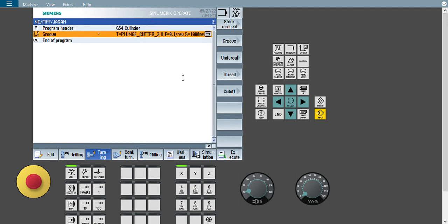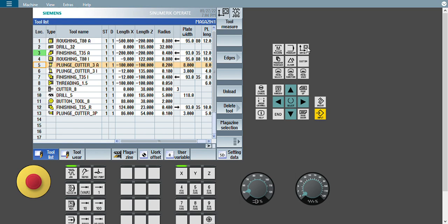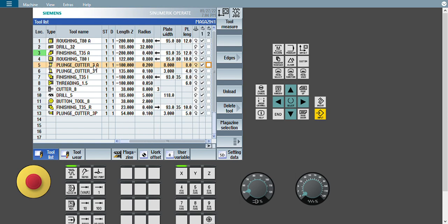And for cross checking purpose, you have to go to offset button and check whatever the dimensions and whatever the inputs are there. Before going to program, we should understand this concept. This is offset, already we took this, and then this is the width of the groove. If width of groove is not particularly perfect for this cycle, then my tool will either take a long amount of cycle time or it will not work. So it should be perfect as per the workpiece and diagram.